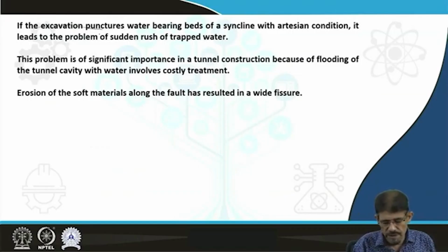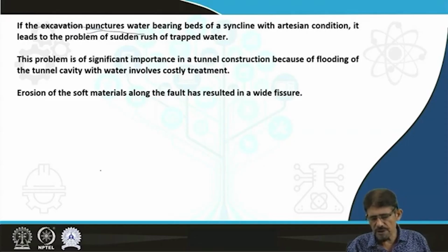If the excavation, particularly in tunneling or creation of the dam foundation, punctures water bearing beds present in a synclinal fold, it creates a lot of problems in the form of development of an artesian or confined aquifer system.